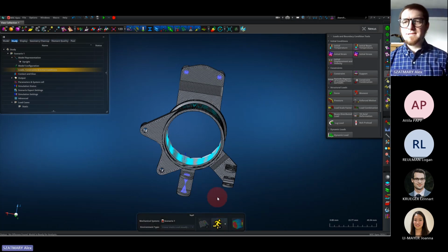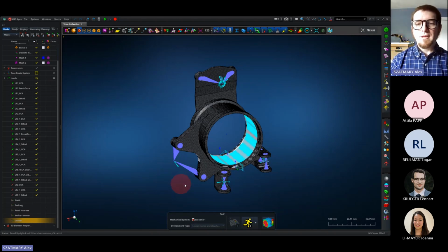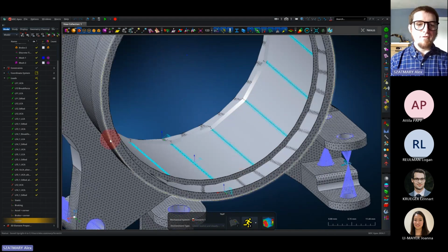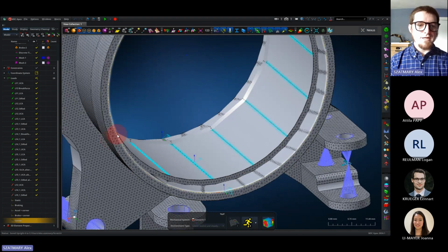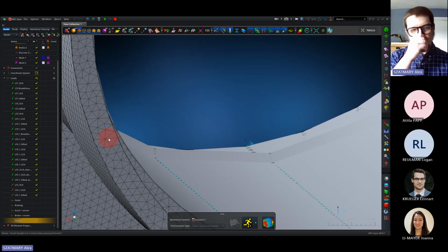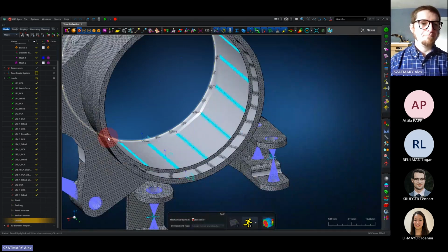That would take a couple of minutes, so let me show you one that I already did before we got to talking today. This is a model that's a little bit more sophisticated. It's the same upright geometry, but let me point out a couple things. One is that the mesh is significantly finer. It's 1 millimeter instead of 2 millimeter. And that makes it so that across this face here, I have about 3 elements going across. This is still looking a little bit coarser than I would like for practical purposes, but it'll do. This is on the coarse end of what would be acceptable.